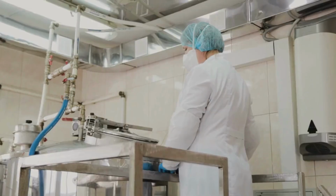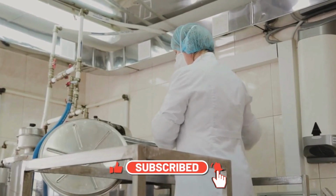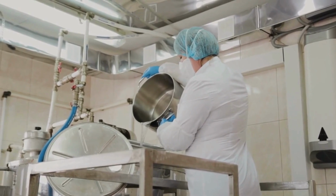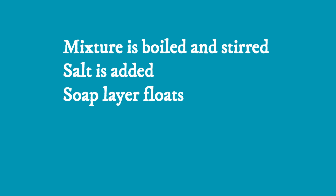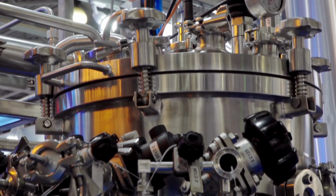The boiling method is still used for specialty soaps. In this process, huge steel kettles, 20,000 to 150,000 liters, are filled with fats, alkali, and water. The mixture is boiled and stirred for several days. Salt is added to salt out the soap, or make it separate from the glycerin water layer. The soap layer floats to the top and is skimmed off. Glycerin is recovered separately.